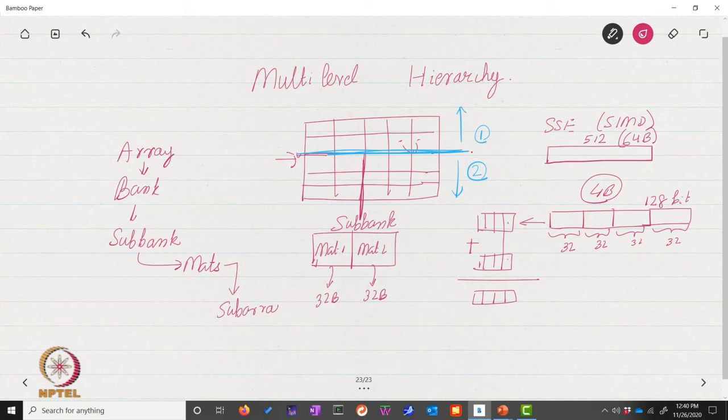So you recall that we had originally divided a bank into subarrays, right? But then we forgot about it. But now the entire picture starts to make sense. So what did we do? Let's start again. We take a bank, we divide it into many small subarrays. We arrange the subarrays broadly into 2 sub-banks or 4 sub-banks. So it depends on how we would like to do. So Cacti of course has some hard-coded values, but in industry they run extensive simulations.